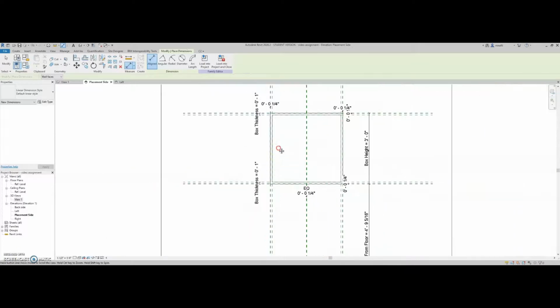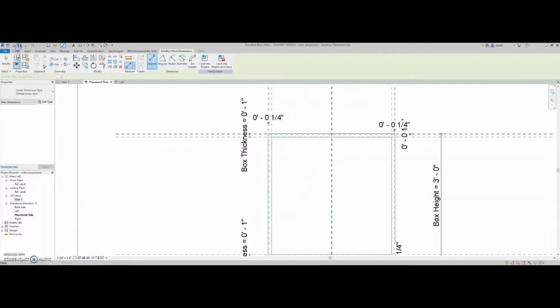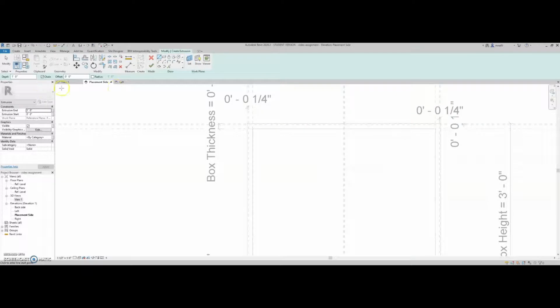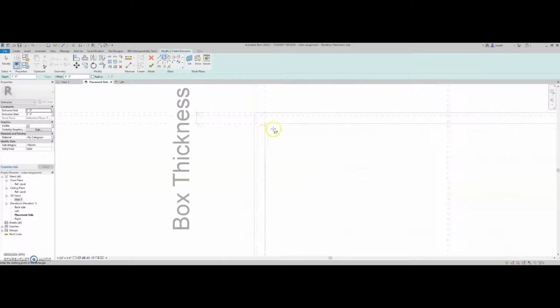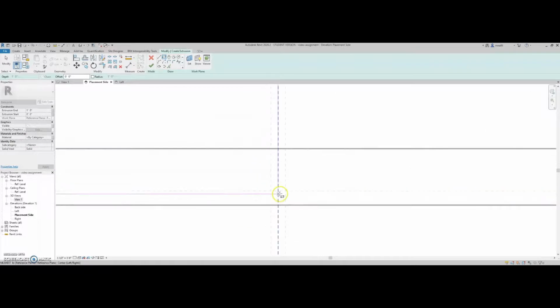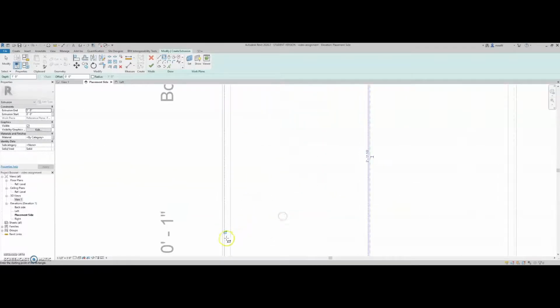Now we can go ahead and add the doors. So we'll go to create, extrusion, and it's really important to set the plane to the face of door. Click OK. We'll keep the rectangle and create a box like so, and we will make sure that they are locked.